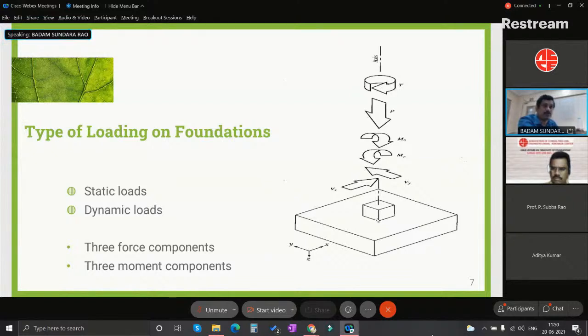One more important point is that even though we are converting into an equivalent joint loading system, the shear force will not be absent. Once we design from the earthquake point of view, especially for the piles, this shear force will be transmitted to the piles in the form of a column shear. The piles will also be subject to shear force, which has an equivalent effect of the moment. At the top of the piles, they should be checked for the shear stresses generated by the shear force at the pedestal level or the footing node level.